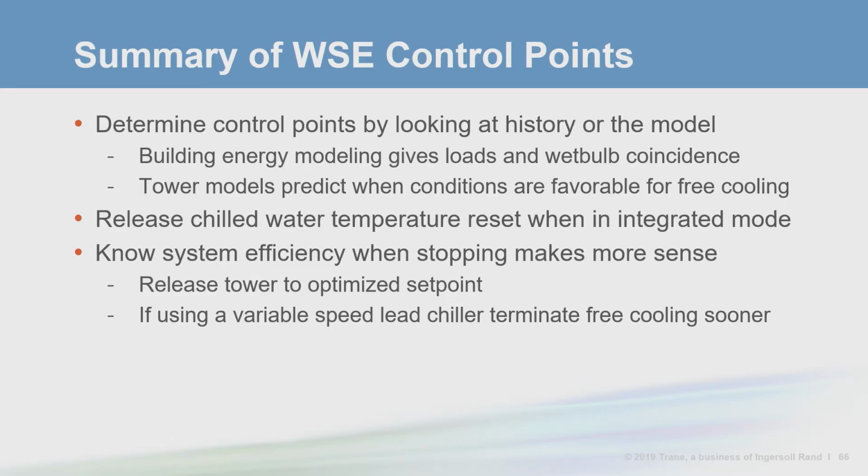And if the lead chiller is variable speed, consider terminating free cooling sooner to save tower fan and condenser pump energy. There are a few alternatives to economizers that may make more sense for your application. The first one is more efficient equipment.